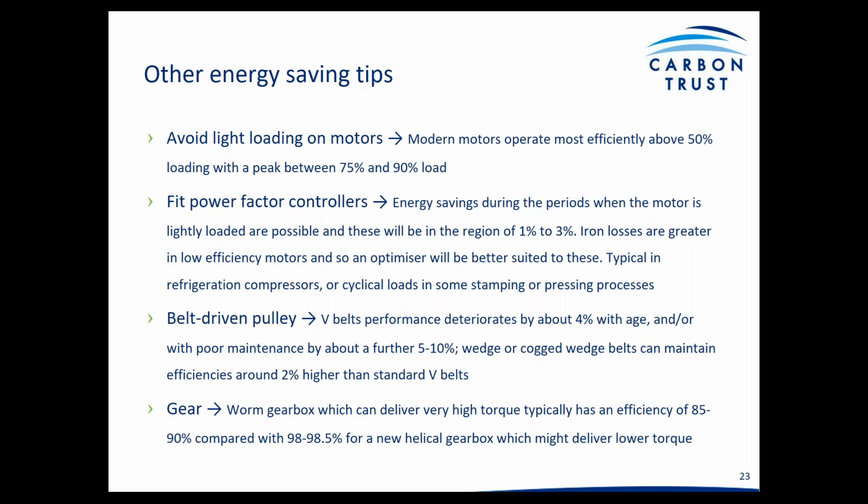Power factor controllers are, again, energy saving devices that, during periods when the motor is not very loaded, can achieve between 1 and 3% savings. This is typical in refrigeration compressors or cyclical loads and some stamping and pressing processes where there are iron losses.